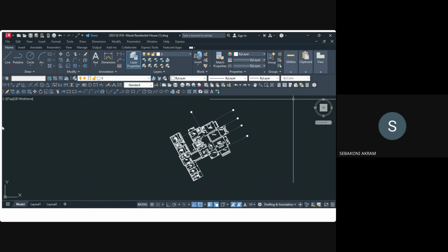You can name it grid, eh? So after you name the layer grid, you come back. We want these grids to come to layer what? You select similar, come to layer. What is your layer? Grid. It's here. You give them grid.